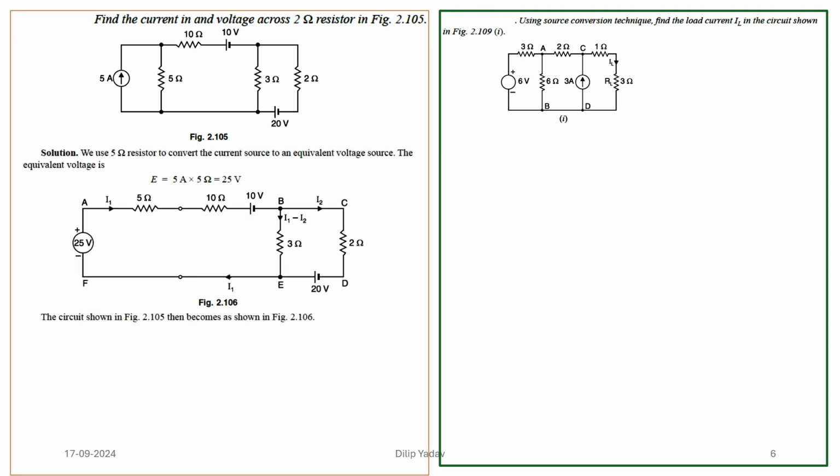What we have done is the same thing, the source transformation from current to voltage, transforming whatever is in parallel so that it is in series with the 10 ohm. It is the same circuit we have taken, with I3 and this is I2. Because the current direction was not given, I can say this is the I1 current, since the source transformation is done now. If I am taking this as I2, we have the two loops, that is I1 and I2.